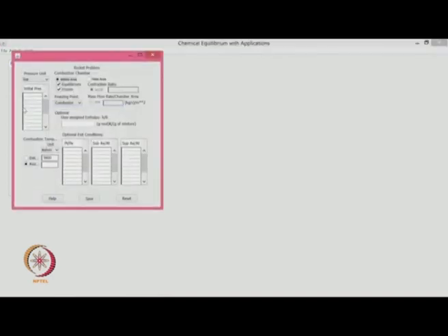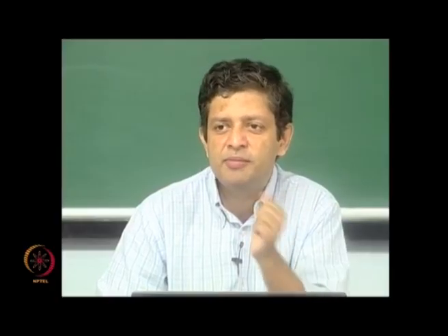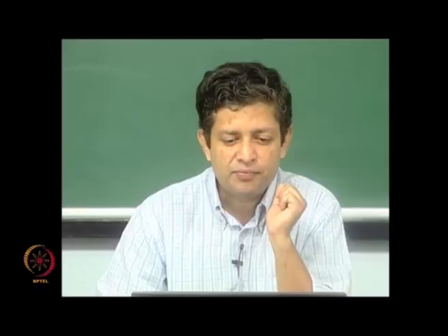So you have to firstly click on this rocket problem. Now this menu opens up, wherein you can define whether you want equilibrium or frozen flow conditions in the nozzle. You can click for both, because the actual situation will be somewhere in between equilibrium and frozen flow.